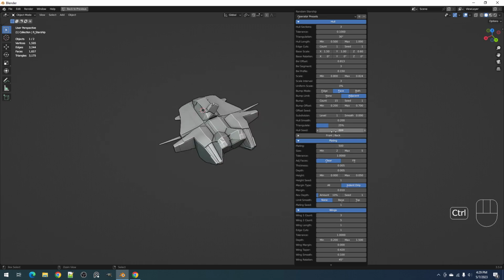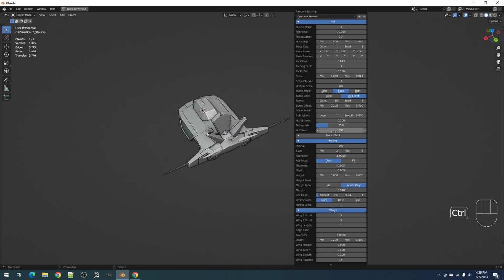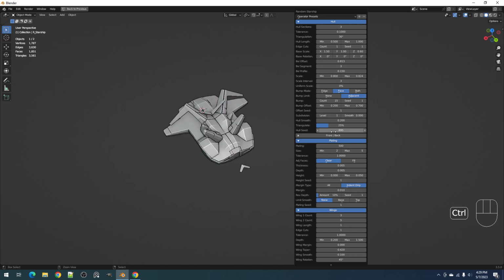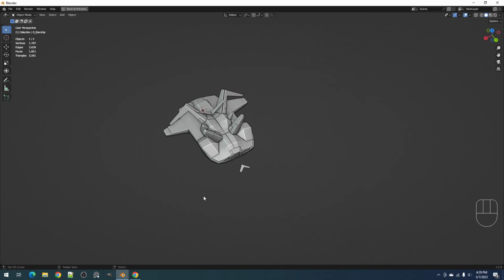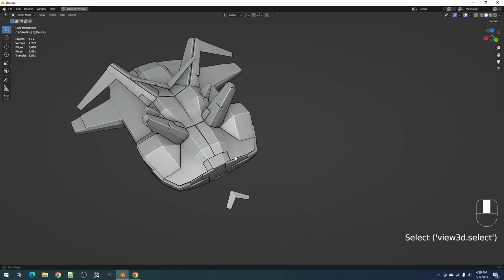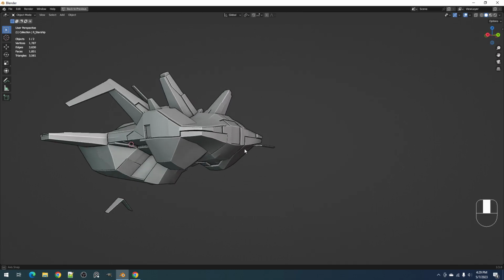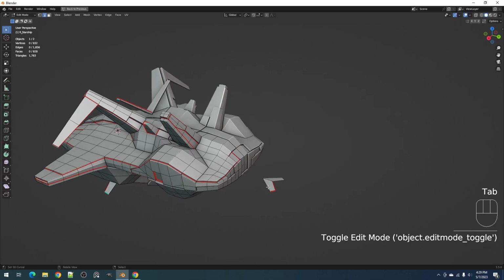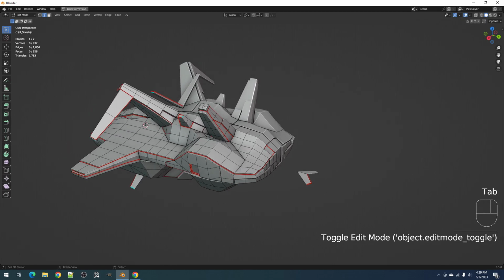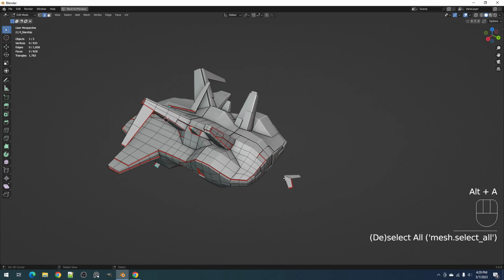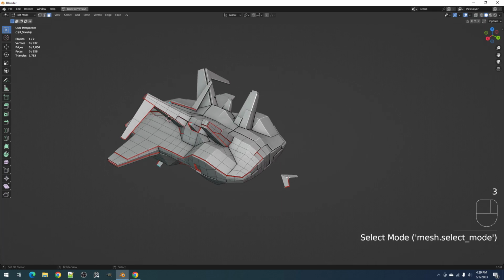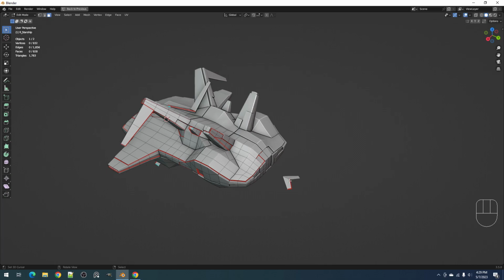So the disconnected geometry, you can randomize them out, or for example, like this one here. If you like the model and the rest of the model, but you have this type of geometry, and you're afraid to randomize the rest of the model, then you can just delete them afterwards. Press L, go to face selection mode number 3, then hover over a face on the separate island.